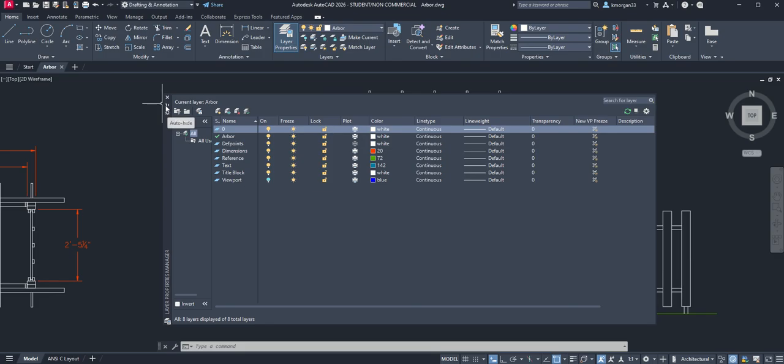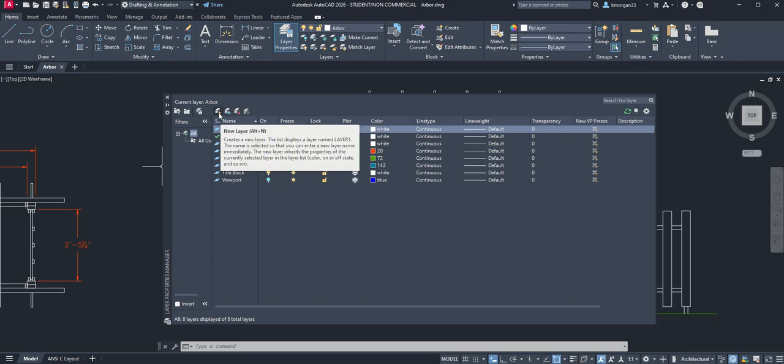The same thing, your auto hide is going to be right here. If you accidentally click on it, you have to hover or open back up to see this window. Okay, right now we are going to add a new layer. So that's a review of your Lab 2. So right here, okay, this is going to make the selected layer current. And then of course this little one with the plus yellow arrow is going to create a new layer. So if you hover it, you can see New Layer.